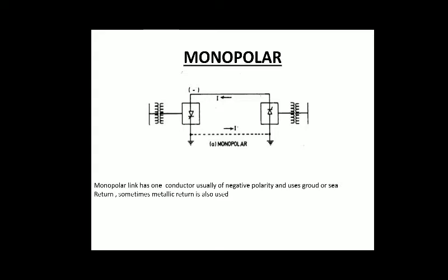And what is this symbol? It is a symbol of a controlled rectifier. If there were no line on the anode side, then it would be a simple diode, but as there is a gate symbol on the anode of this diode, it is not a diode, it is a controlled rectifier, a silicon controlled rectifier. And with the help of this rectifier, we control the output power.